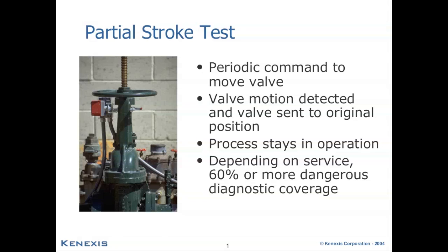So when we send that periodic command for the valve to move, we're going to try to detect that motion has occurred. And once we are able to ascertain that either motion has occurred or it's not going to occur, which is another important factor that you need to consider, we're going to send the valve back to its original position.